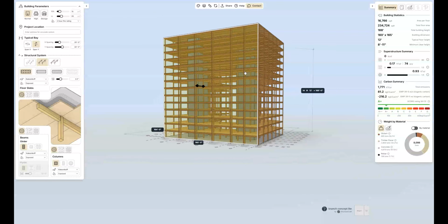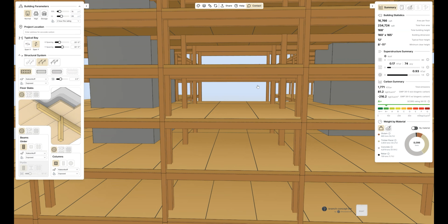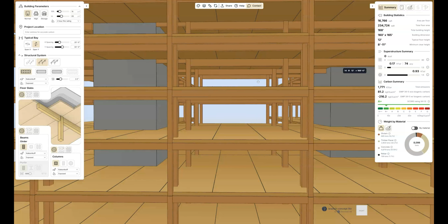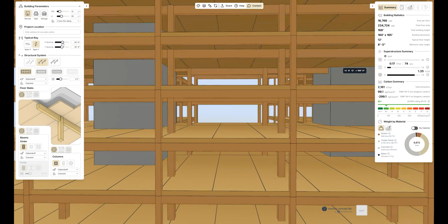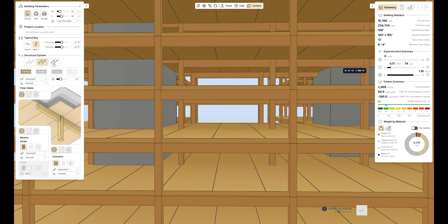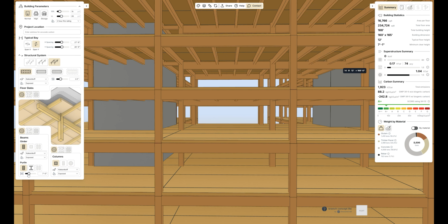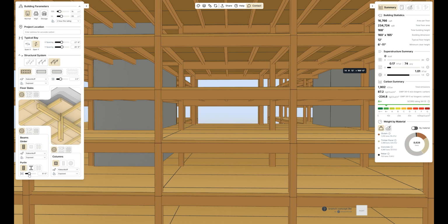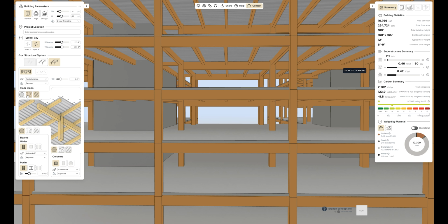Grid sizing controls the structural layout of the floor systems. Use the X and Y spacing sliders to adjust the distance between the grid lines in each direction. This affects how far your beams and slabs span. Purlin spacing is available for purlin on girder systems. It lets you define the secondary support spacing on top of the primary grid. Adjusting these values helps balance material efficiency with structural performance.